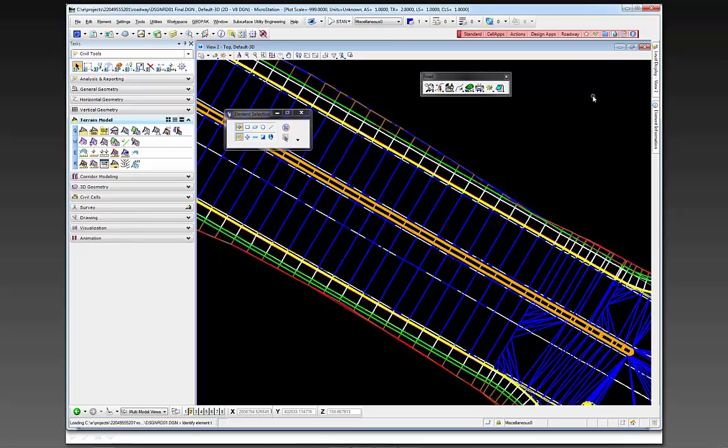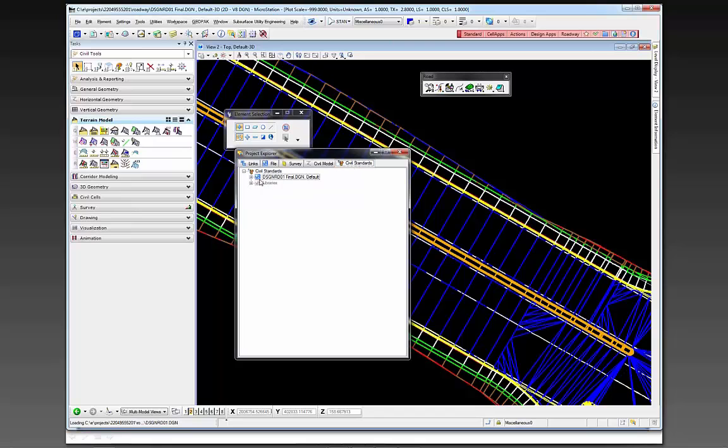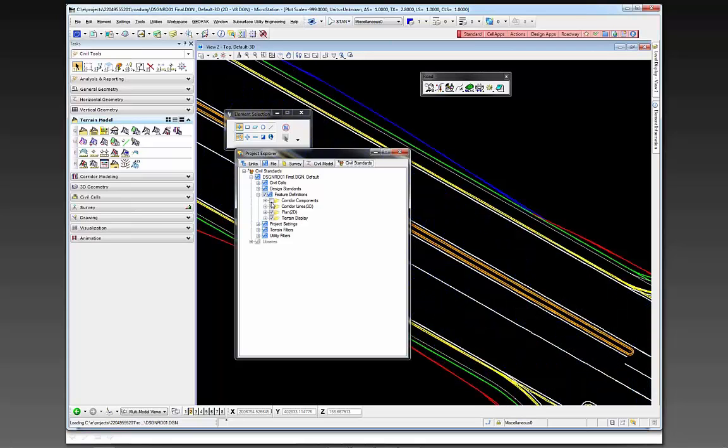We also, if you remember correctly, in the Project Explorer, I've talked about this several times, we've organized our features by corridor components, corridor lines, 2D lines, which are 2D and profiles, and then also terrains. So really all you'd need to do is leave on the corridor 3D lines folder, and you would have pretty much everything you need, but you might have more than what you need. Okay, so if you turned off the corridor components this way, it's going to turn off all those meshes.